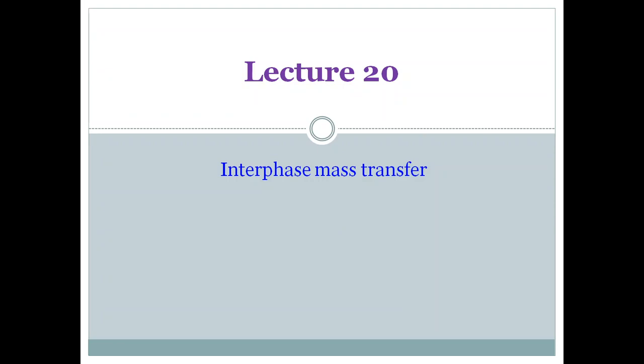These are capital Kx, capital Ky accordingly, and thereafter we made the material balance for four systems: steady state counter current, steady state co-current, then steady state cross current, and thereafter we have seen how we can construct multiple stages in a single column.